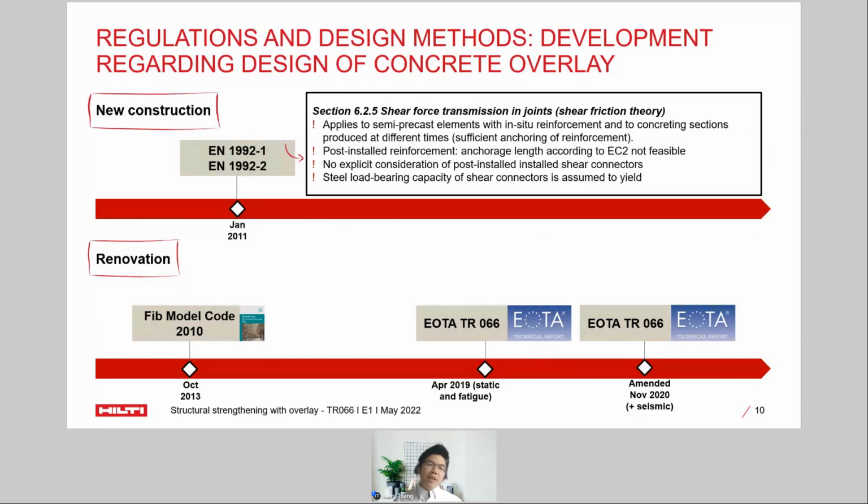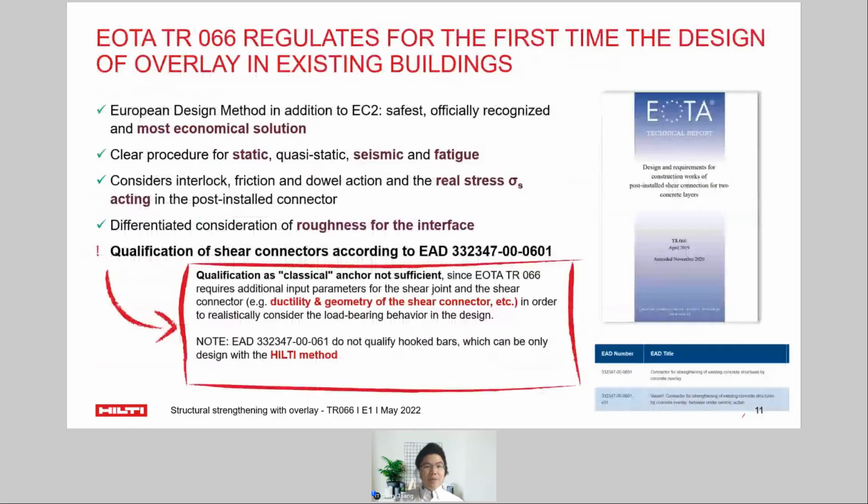It was first published in 2019 with static and fatigue design, and later in 2020 it got the first amendment, including the seismic design. Today we will mainly focus on the TR66 design method. TR66 is the first time regulating concrete overlay in existing buildings. This is the European design method. In addition to EC2, it is the safest, officially recognized, and most economical solution. It has very clear procedures for how to design the static case, seismic case, and fatigue case.